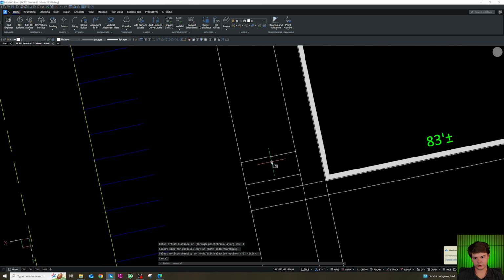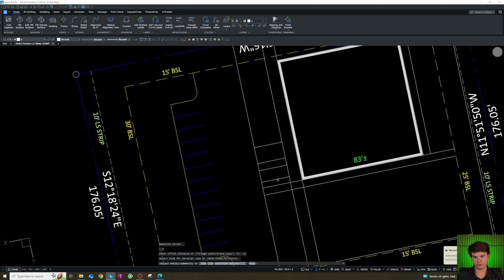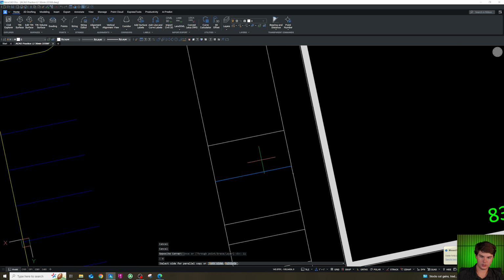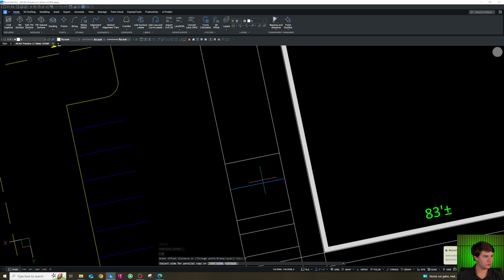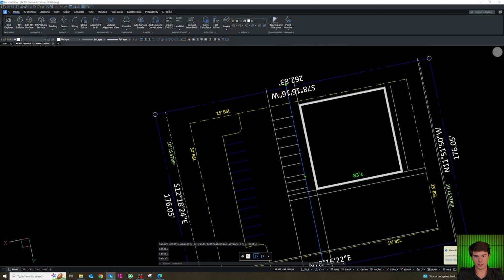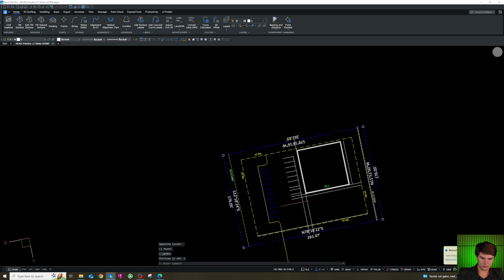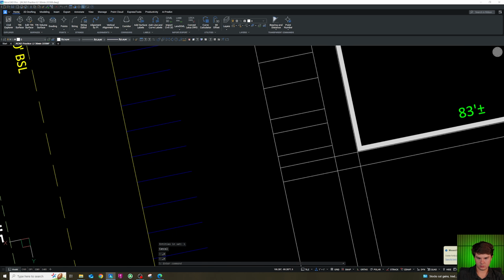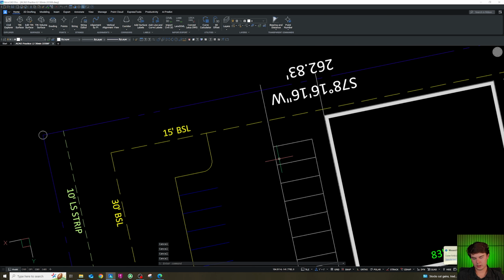which we do an 8-foot spot, 5-foot hatch, 11 feet for the van, and now we'll do 9 feet for normal parking, which we have 1, 2, 3, 4, 5 more spots of. 1, 2, 3, 4, 5 spots. I can bring this all the way back down to here. I can trim this away right here, trim that away there.